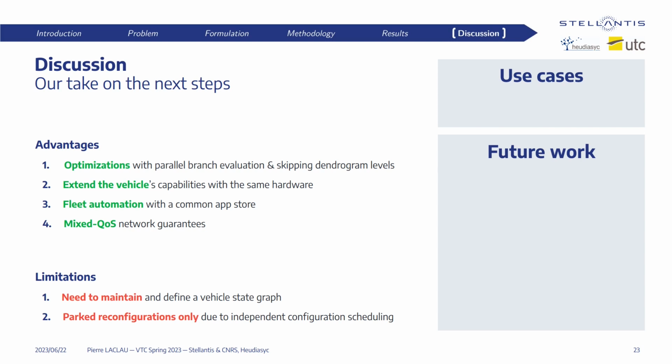However, there are two limitations. The one is that there is a new concept, and then engineers need to maintain this new vehicle state graph, which can be generated, but there's also some work to do. And also, since every configuration is treated completely independently, you cannot reconfigure while the vehicle is driving, because you have maybe buffer usages that may be different. You haven't predicted what's going to happen. And so, of course, it's limited.